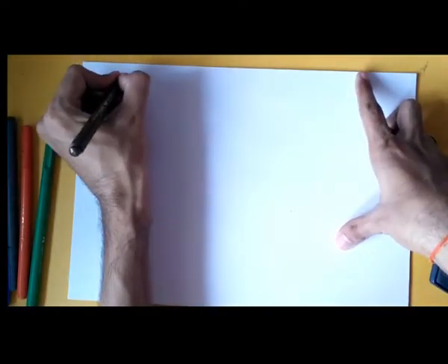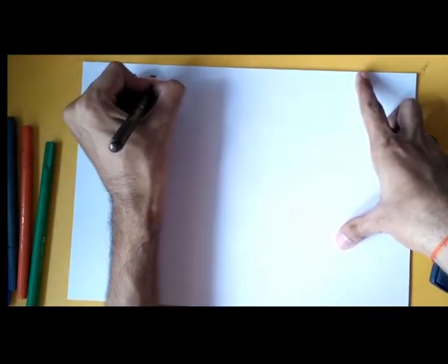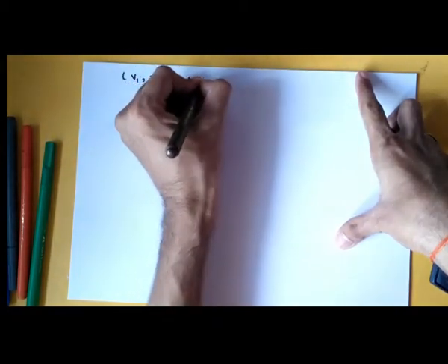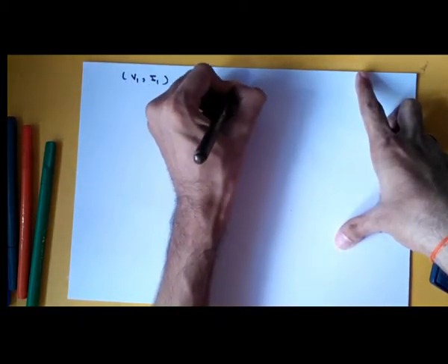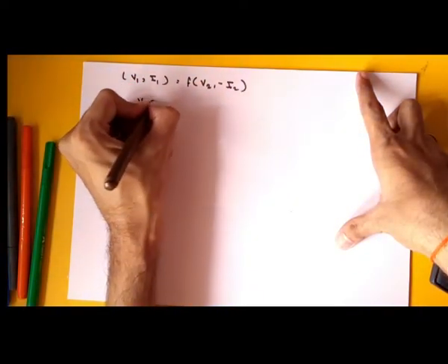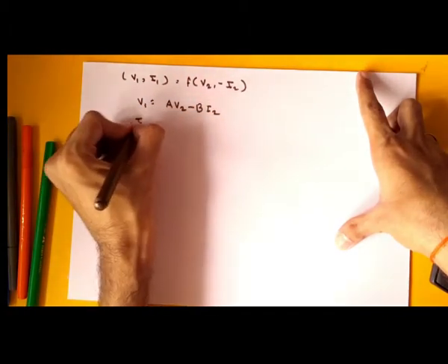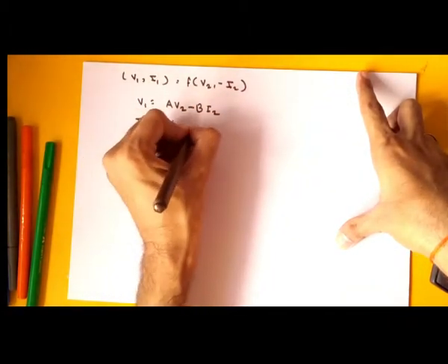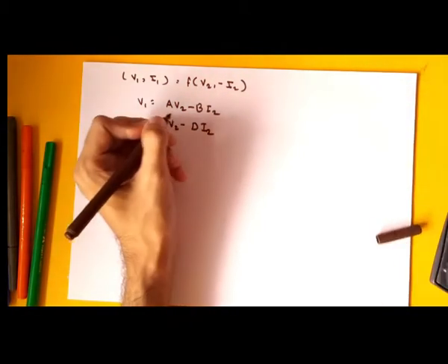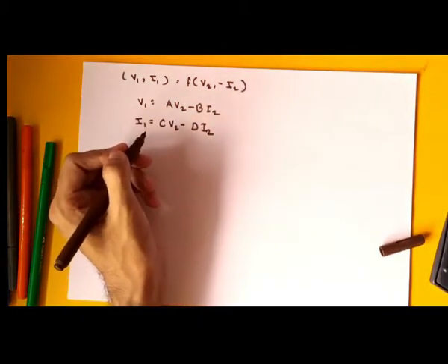If you remember, in Z parameters we saw the condition of reciprocity and symmetricity, right? The same thing we will see here. First let's write the equation. For transmission parameters, V1, I1 is a function of V2, minus I2. So V1 will be A V2 minus B I2, and I1 will be C V2 minus D I2. Right? So then obviously you can write this in matrix form.